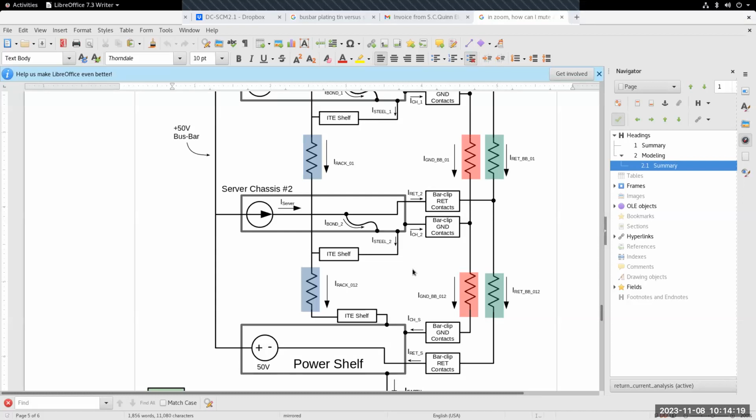There might be another loop on the source side, with your neutral and ground in a Y-based system. What he's talking about is the potential difference between neutral and ground, which are tied back together at the ground bar right at the transformer. I forget what the spec is there. I think it's either 3 to 5 volts of potential difference between neutral and ground, and that's what imposes a limit on that current.